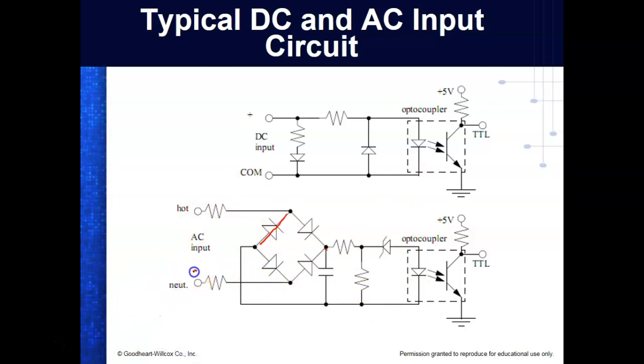So if I put the minus down here and the plus right there, it would flow through this resistor that's in there for protection. It wouldn't go that way. Why? Because it's against the arrow, right? It'd go this way. Wouldn't go that way because it's against the arrow. It'd go this way. And it goes through what? Same direction. Comes through this, comes back. Now what it's doing, it wouldn't go through this one because this is where it came from. So it'd come back this and go back to the positive. So that's the rectifier. This is what's in your car.